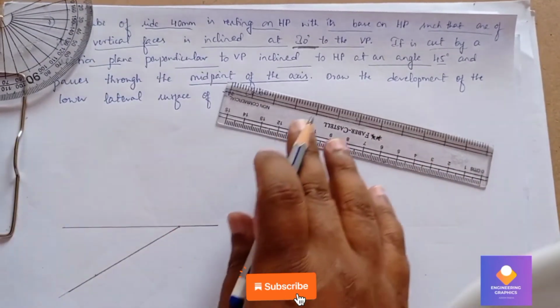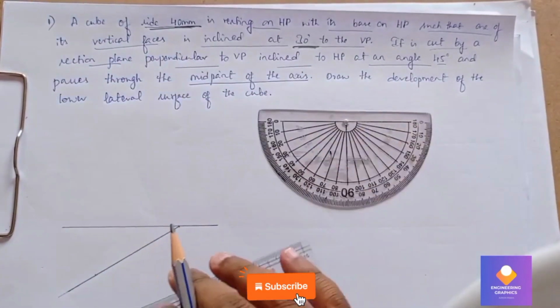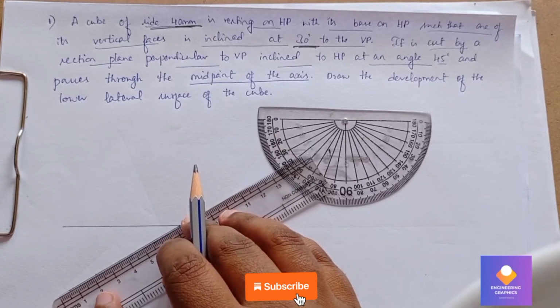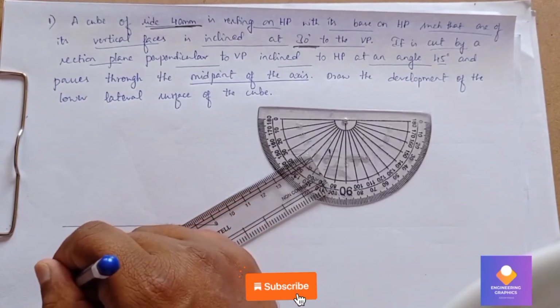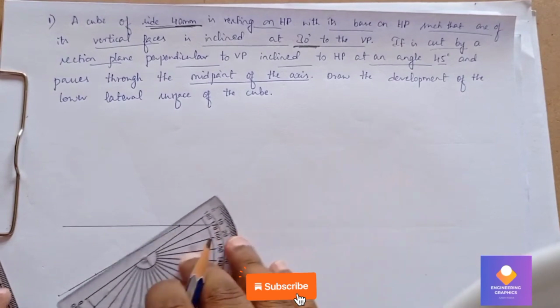So mention angle 30 degree here. Okay, so we need to draw a cube of side 40. So cube of side 40 we have to draw here. So exactly at 40 mm we need to draw here. So 40 you have to mark. So these edges were exactly vertical.